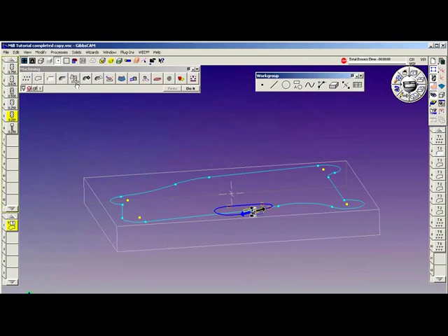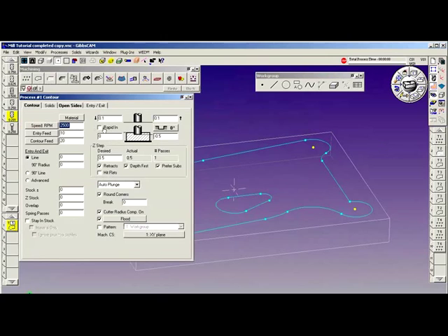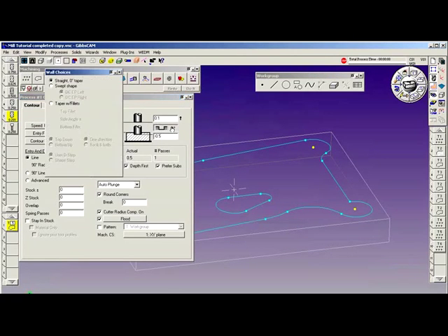Now, what I'm going to do is open the process dialog, and go to wall choices. This button here gives me a set of options for machining swept shapes, tapered wall with fillets, and straight with zero taper, which is the default. That's why you see the 0 here. My selection is going to be tapered with fillets. Give me the ability to create a radius at the top, side angle, and a bottom fillet. I'm going to go with a 100,000th top fillet, a 10-degree side angle, and a 0 bottom fillet. The bottom fillet will be created by the radius on the tool.